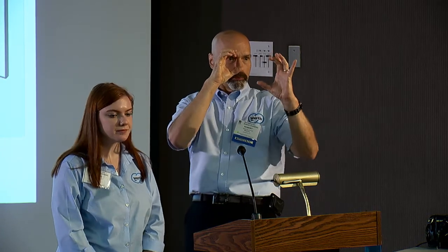Artifacts like cone beam effect and beam hardening, yes, there is an algorithm that we've created, and also other people have, but Werth was one of the first companies to come out with autocorrection. So we put a correction curve based upon material, voltage, known facts of the scan process. And it's another algorithm that goes upon other algorithms to do all the reconstruction, but we're able to take out artifacts. But it's like a camera. If your picture is blurry when you're taking it, no matter what kind of software you have to reconstruct it, Photoshop, it's still going to be a blurry picture.